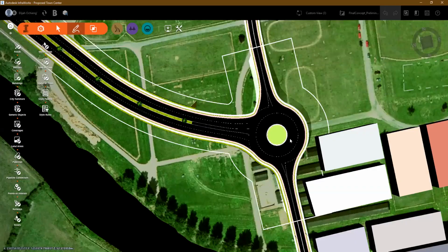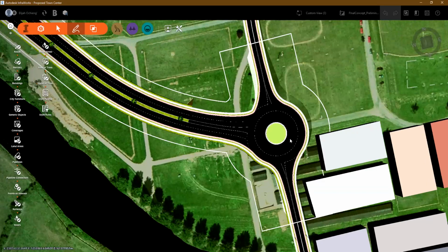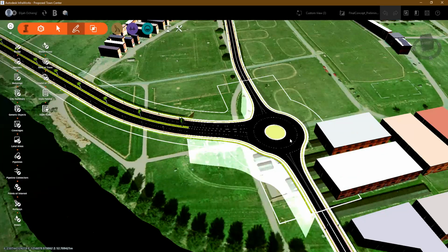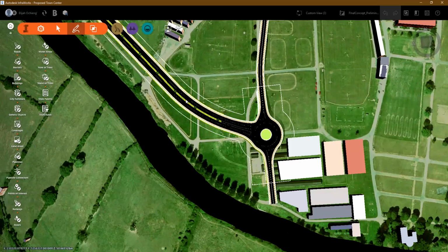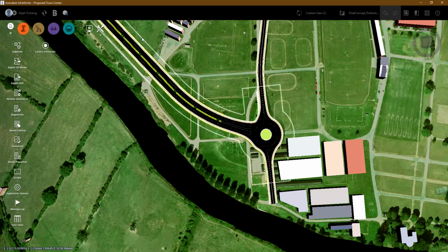the next stage is to link this up with Civil 3D so that you can produce the details and generate the various reports that can allow the surveyor to stake it out and come up with the correct route based on what you have designed on the software. So to do that, we need to link this up into Civil 3D. And the basic level of exporting this into Civil 3D, we use what we call IMX.